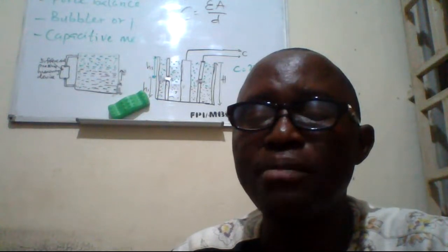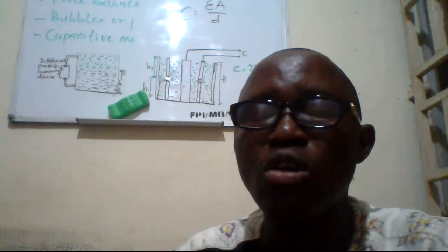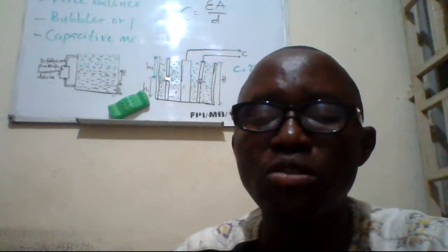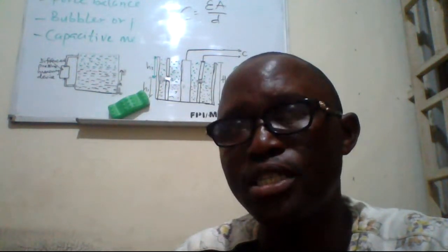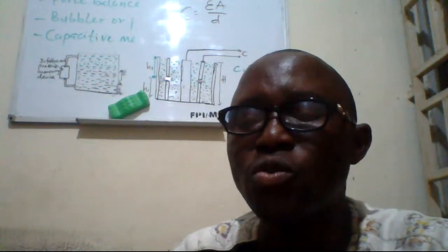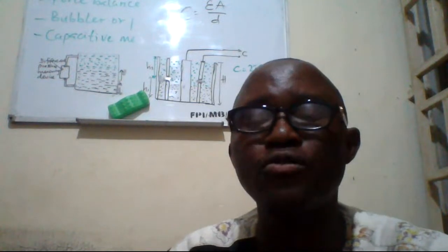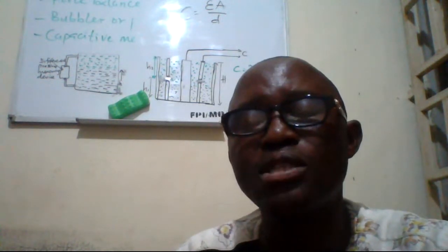The air pressure in the pipe is equal to the hydraulic head of the liquid, and this can be measured with a standard differential pressure transducer. All right. So the liquid level is computed using the mass density of the liquid. So that is how the system works.